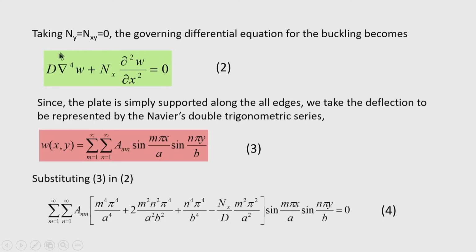Now, you can note here, for buckling analysis we have not considered any transverse load, because this is a homogeneous solution of the differential equation that will yield the buckling loads. After imposing the boundary conditions, the buckling equation, the characteristic equation that forms, is a homogeneous type of equation, and in most cases you will find the equation is formed in the form of trigonometrical or hyperbolic functions.